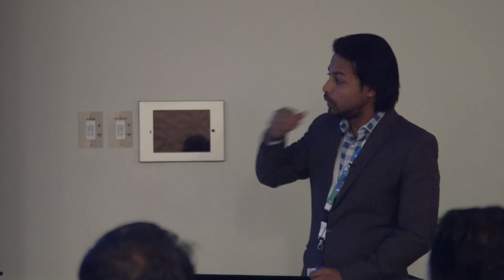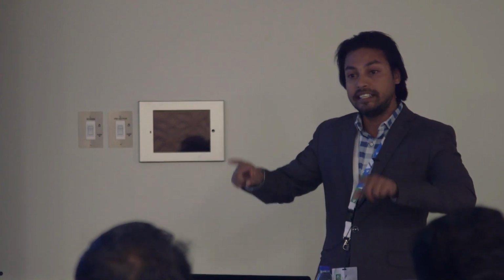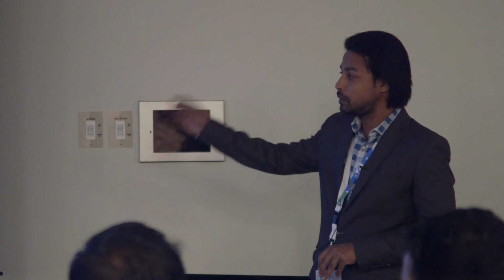And then you can actually create it. One of the tools, like Door Factory, does this: every time you have to go back, create a new family, you start drawing your reference plane, choosing what extrusion or sweep it is. What this tool does is, you just specify what type of frame you require, what type of panel you require, and what the sizes could be, and then it creates a parametric door for you. You will see a decent user interface where you can select the options that you need, and then you customize and you place it.